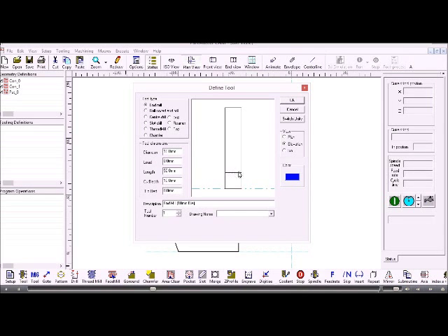And this line here represents the maximum cutting depth. So we could use that value to control the number of passes that are used in the Z-axis. Tip radius, if we need to use a tip radius we can enter it there, but in most cases for a standard end mill that would be 0. When we use the term end mill we can use that for any type of standard milling cutter. Could be a slot drill or it could be an end mill, the same thing.